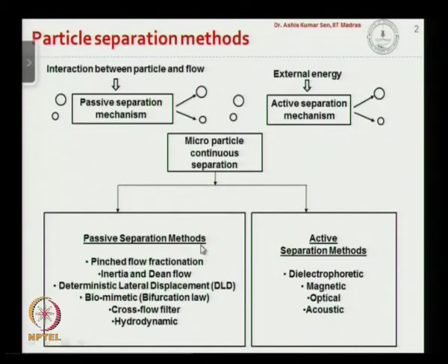So, as you can see here, microparticle separation is broadly classified into two categories. One is the passive separation. The passive separation mechanism does not use any external energy, it uses the interaction between particles and the flow to separate particles based on physical properties. Then we have active separation mechanisms which make use of external energy like electric field and magnetic field to separate particles.